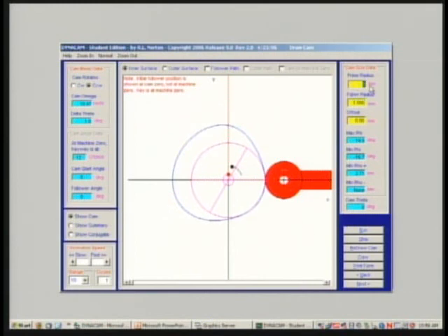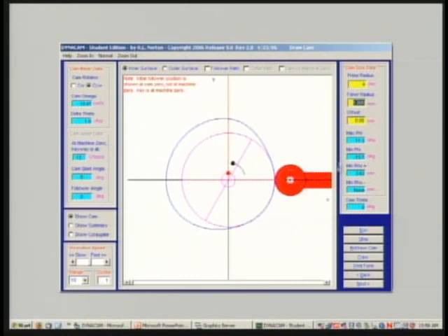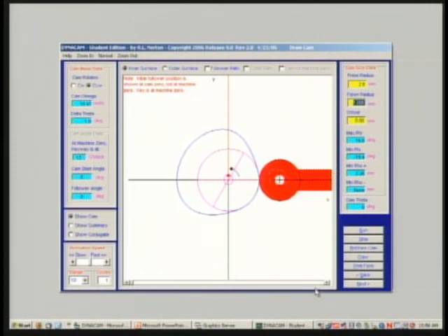If I go larger, if I go to 4 inches, for example, the penalty I pay is I have a bigger cam and maybe harder to package. The gain I get is my pressure angles go down and my radius of curvature goes up. I don't think this is necessary for this particular cam. I think 3 or perhaps even 2.5 might work if you wanted to get a smaller package.